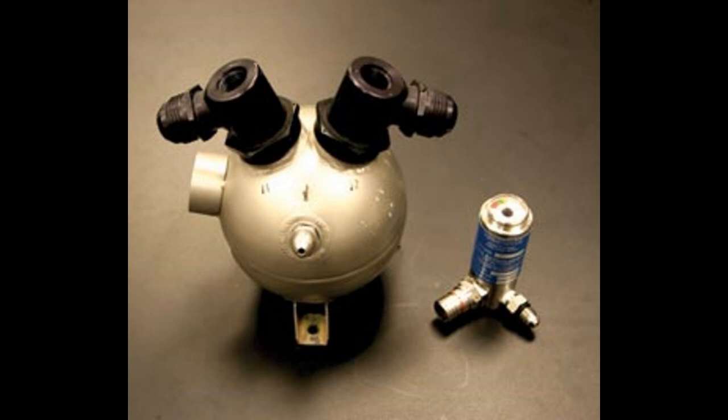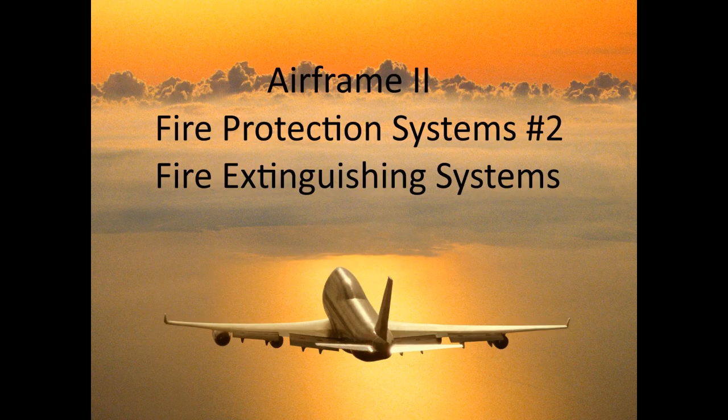The Fostex fire suppression system is less complex than the halon system. It's designed to be maintenance free for 10 years. After 10 years, all we're going to do is swap in a new Fostex container and continue on with our lives. This eliminates the typical hydrostatic and visual 5-year inspection associated with the halon systems. So this has been really an exciting development in fire suppression for aircraft. And you can go online, here are a couple links. You can go online and read more about that.